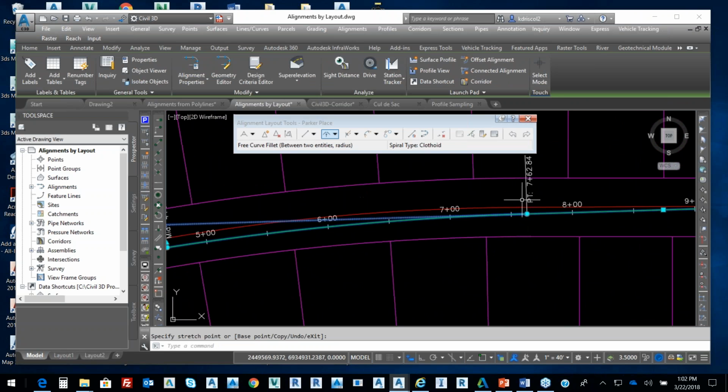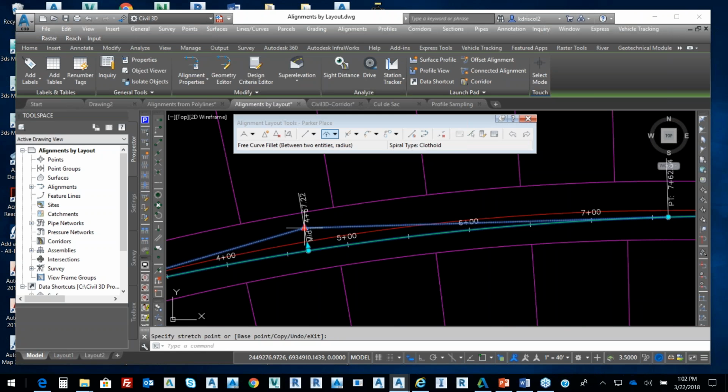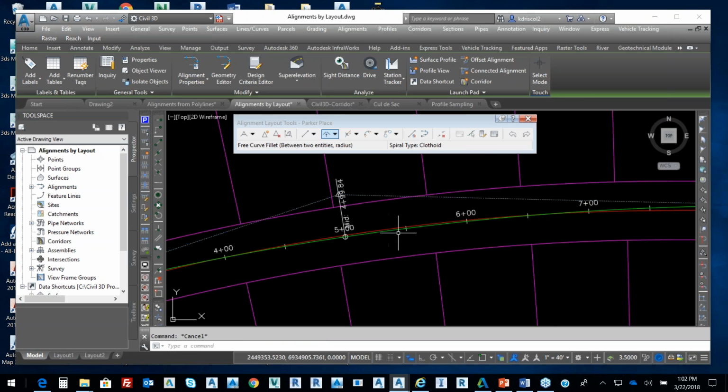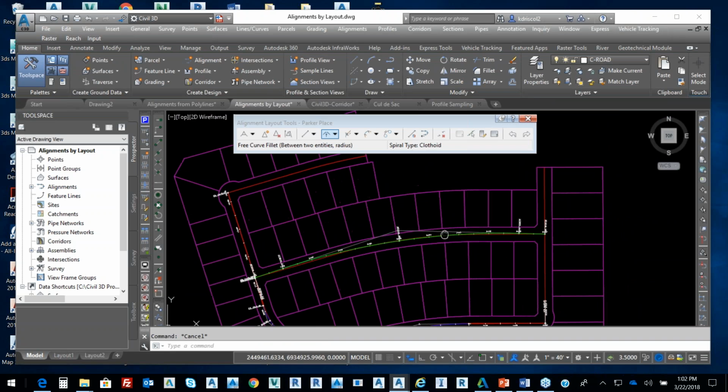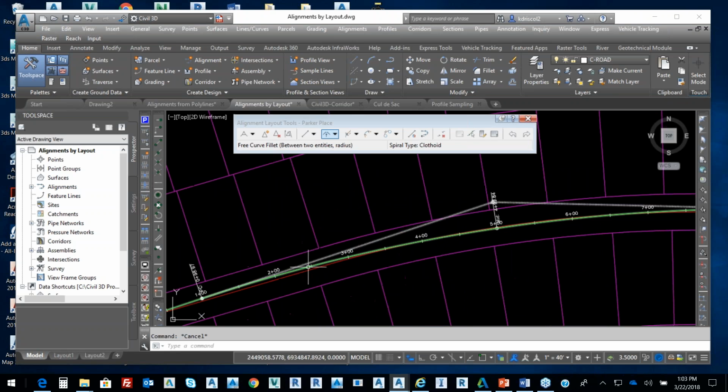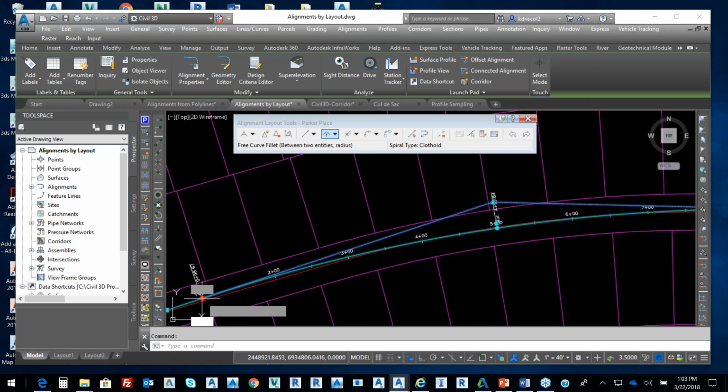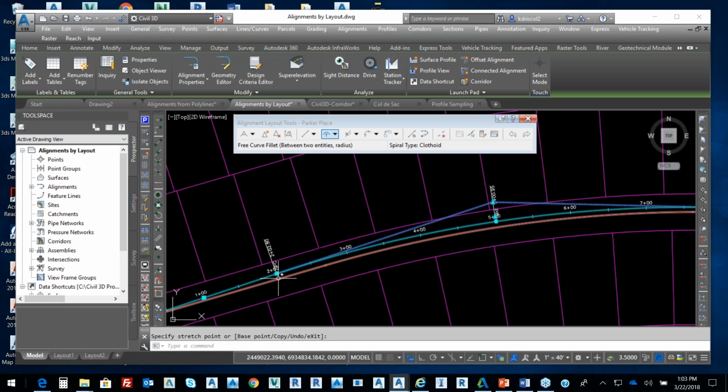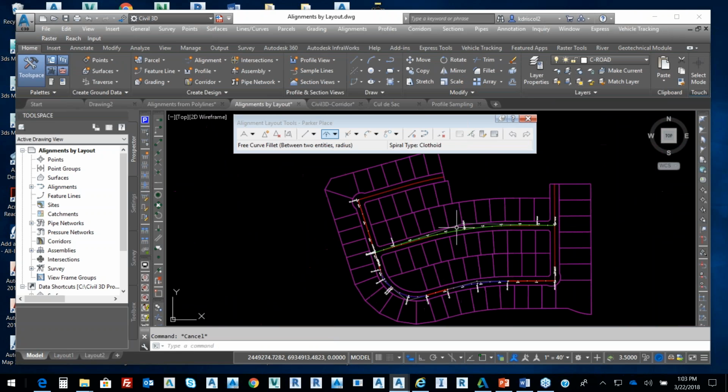And we'll make that curve a little bit bigger. Someone giving me data, move that over a little bit. And I'm right there. And clearly, creating curves and data from polylines is going to be an issue, but they may not be tangent. They may not be based upon my design parameters. So we definitely want to consider those things. So if we came back down, move this back up a little bit. And then let's change the radius here. So we can just get it close.